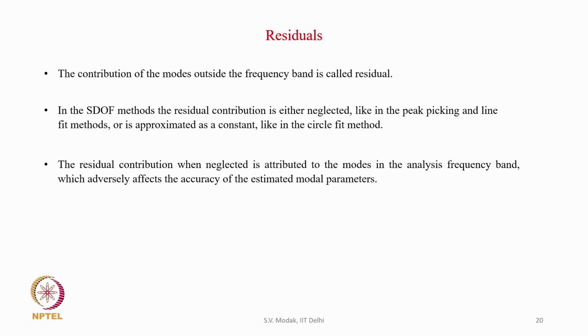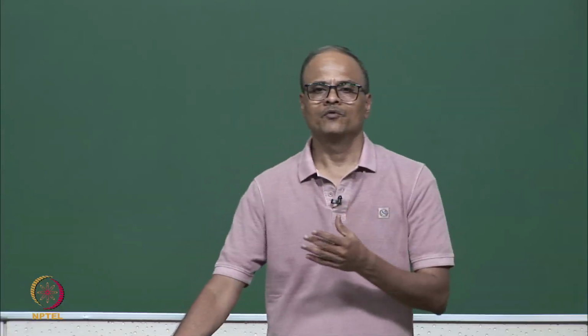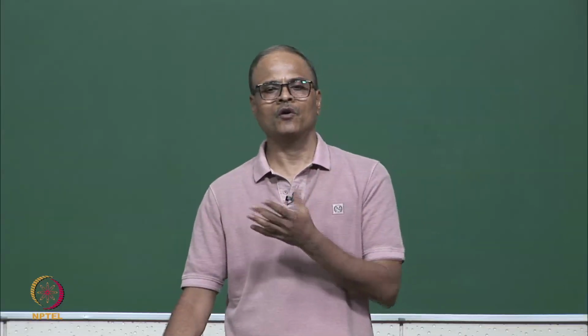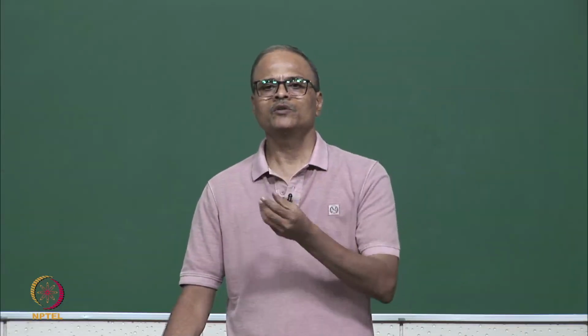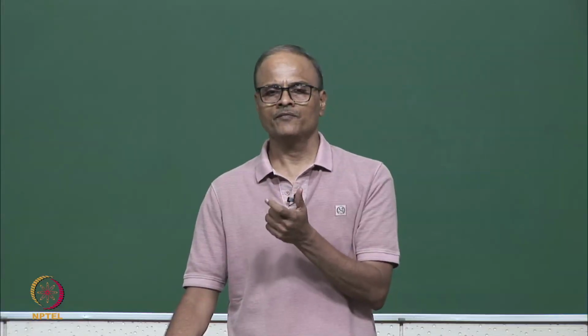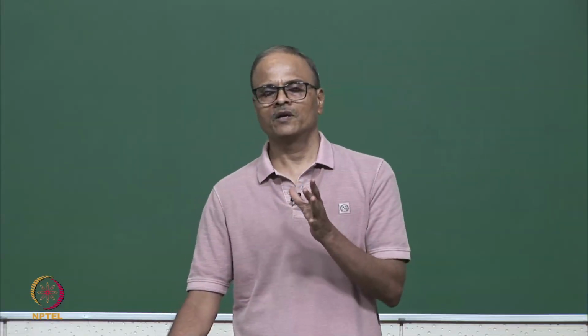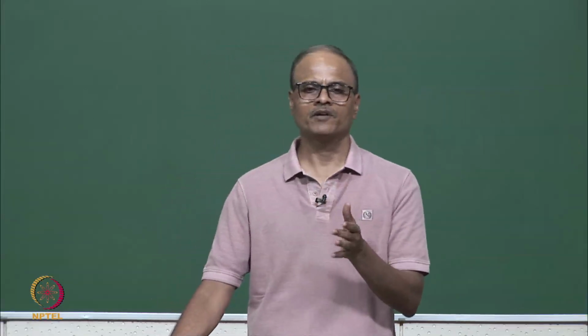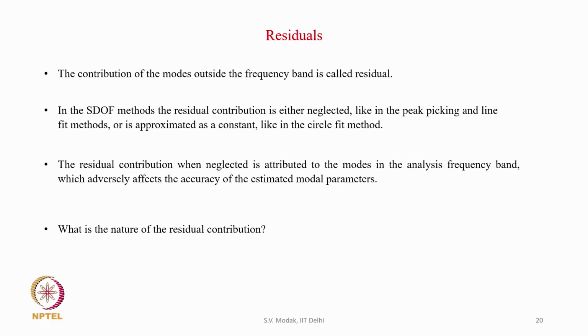However, the problem is that if the residual contribution is neglected, then that contribution is attributed to the modes in the analysis frequency band, and this adversely affects the accuracy of the estimated modal parameters. So, when we neglect the residual contribution, we are attributing the contribution of all the modes only to the modes inside the frequency band, and this distorts the fit and affects the accuracy of the estimated modal parameters. So, let us first look at the nature of the residual contribution, and then how it can be approximated for modal parameter estimation.